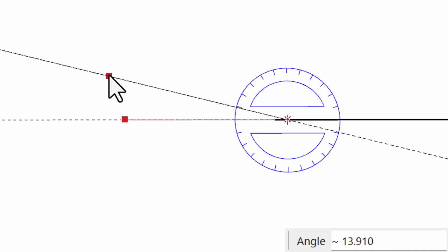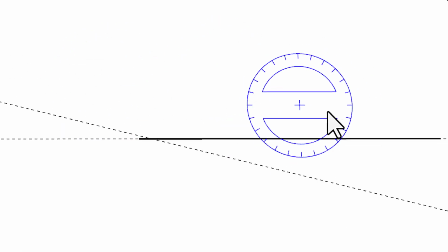That means there are more decimal places. SketchUp is not able to report back any further than to the 1,000th of a degree. So basically I get those 3 decimal places for my angular precision, but the tilde lets me know there are more numbers that come behind that. Like I said before, keep that in mind. That's going to come into play when we get into CAD. All right, same thing over here.